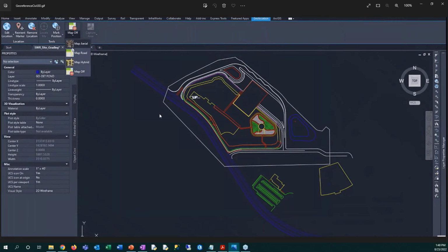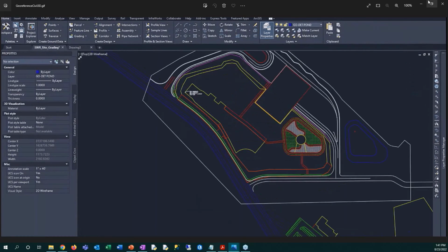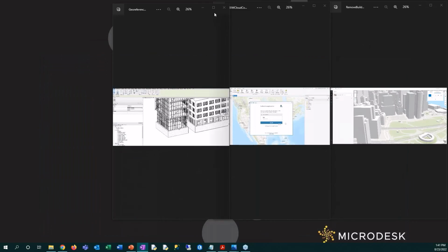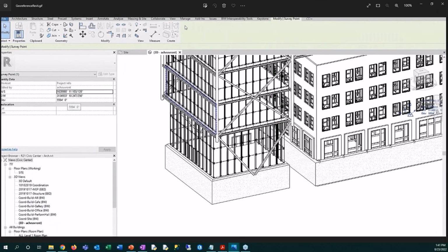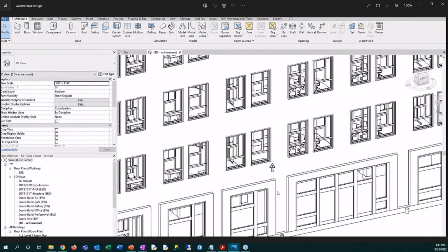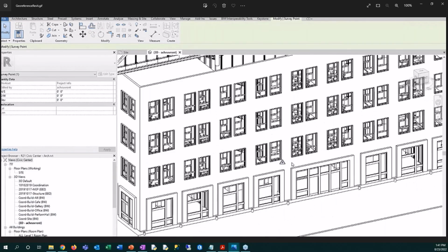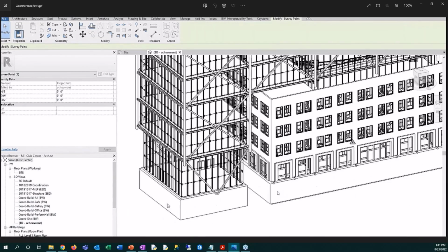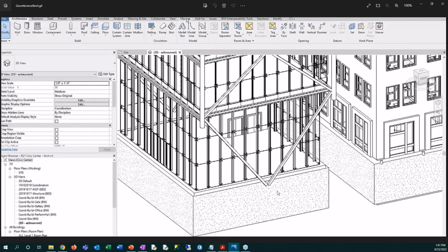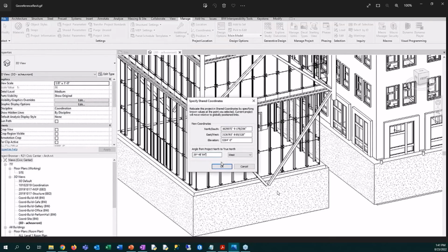Next, we're going to see how to do this from Revit. Now, from the Revit side, we're going to first zoom into our survey point. The survey point has a default of 0, 0, 0 coordinates. We're going to unclip that. And we're going to find a point and use the Specify Coordinates at a Point tool to define the real-world coordinates at that footing point.